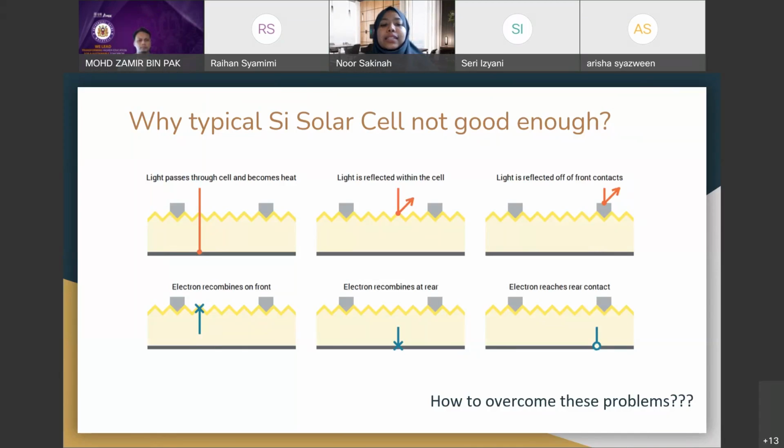So as you all can see, these plain silicon solar cells encounter a few efficiency losses. Based on the upper part of this diagram, these are inefficiencies with capturing sunlight, as the sunlight can be reflected from the solar cell itself, blocked by wires, or sometimes go all the way through the cell and turn into heat. Thus, it reduces the cell efficiency.